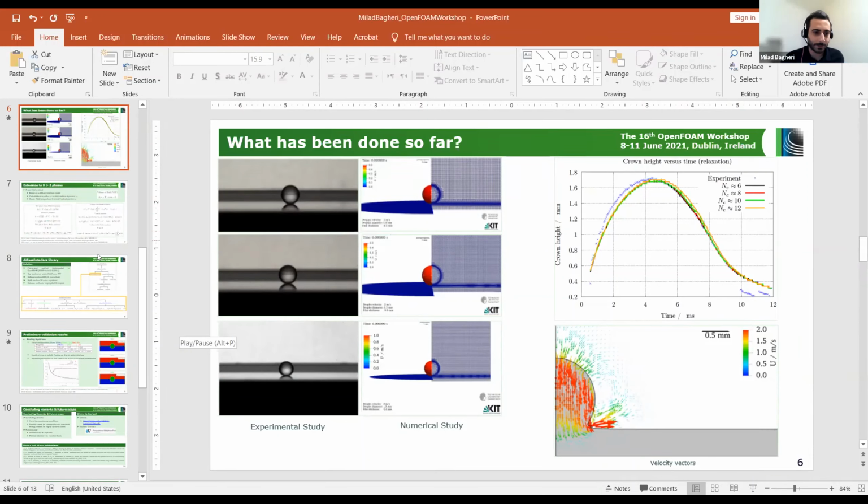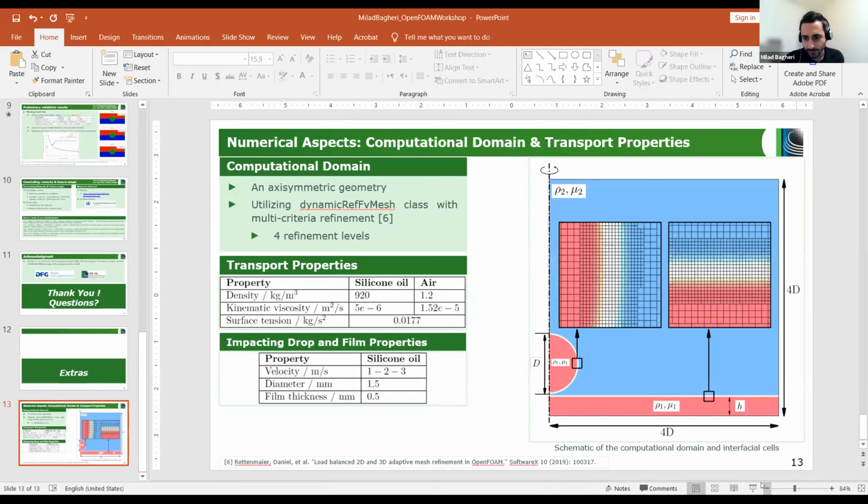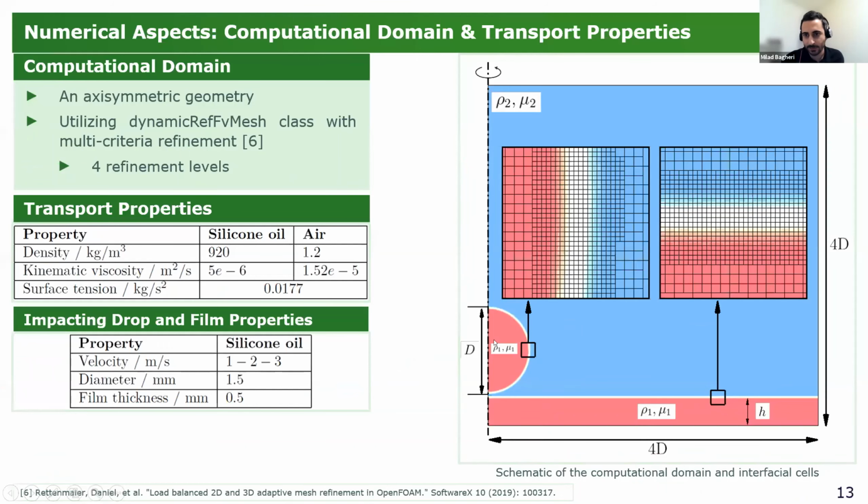Okay, so the NC stands for, maybe I can show it here. In diffuse interface, you really need to capture the interfacial layer with sufficient cells. So if you look closely, we have this NC. This is what's referred to as the approximate number of cells that are used to resolve the interface for that simulation. And the step.